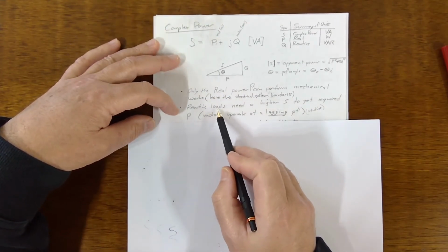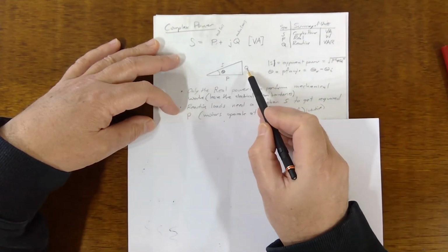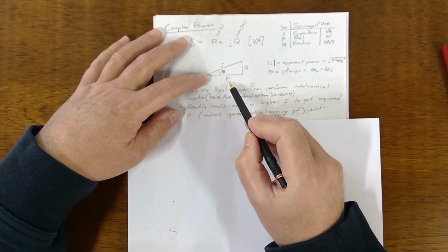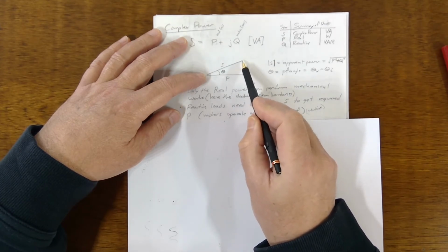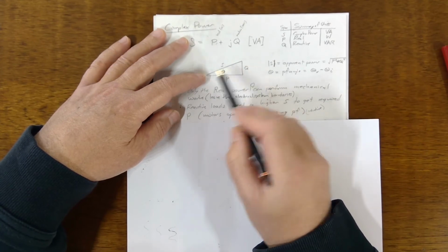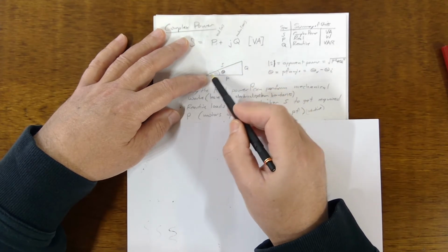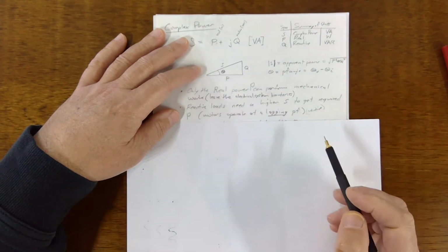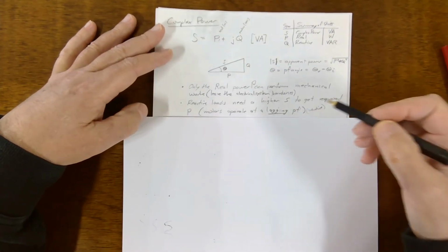Anyway, the reactive loads, Q: the bigger Q is, the bigger S is going to have to be to get the same P. You're trying to send power to some device that's using up P, but there is reactance Q in the circuit, which means some of the power is bouncing back and forth. So imagine, the bigger Q gets, the bigger S has to be to maintain the same horizontal P. This is typical with motors, industrial motors, or even little motors in your house.